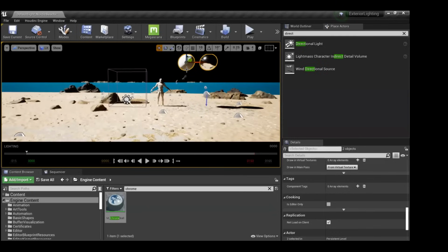Yes, this is the screen space GI, which we enabled. I can show that also. If you press the tilde key, which is above the tab key, you can control all those things from here. If you want depth of field quality, you can control it from here. If you want SSGI quality, you can control it from here. If you want all your meshes to display the highest level, which is LOD 0, you can do that here also, like forcing all the meshes to show LOD level 0. You can control all those things in the command window.